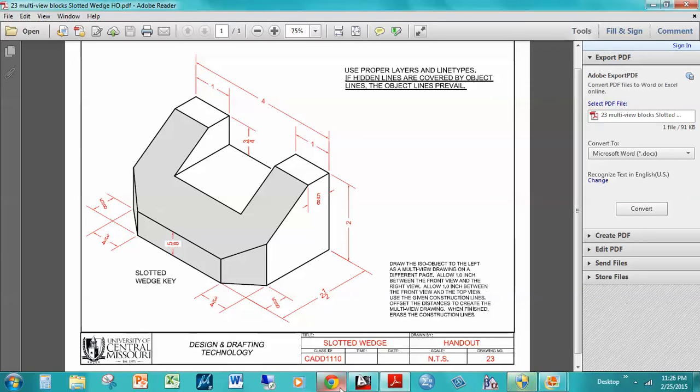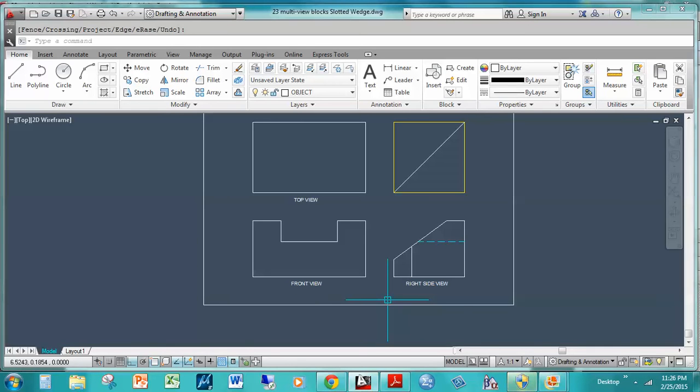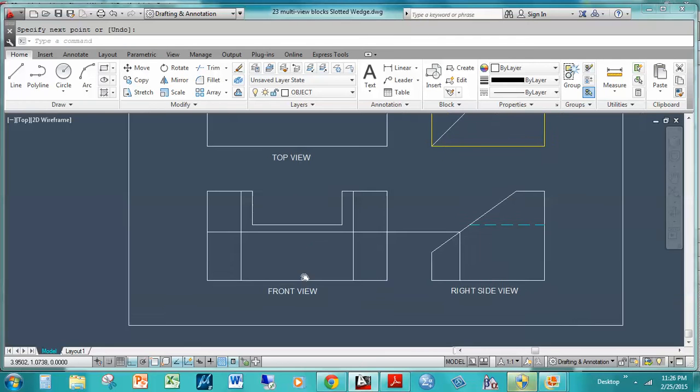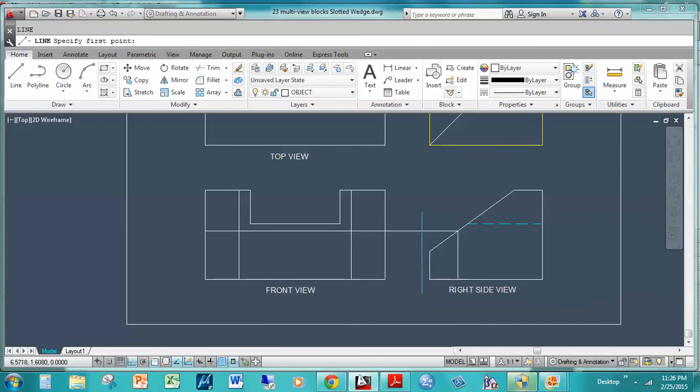So we can offset 0.75, enter, from here to here and from here to here. Also, we can draw a line from this point to this point. Okay, and here at the bottom we actually have 0.625, right? That aligns with this point.